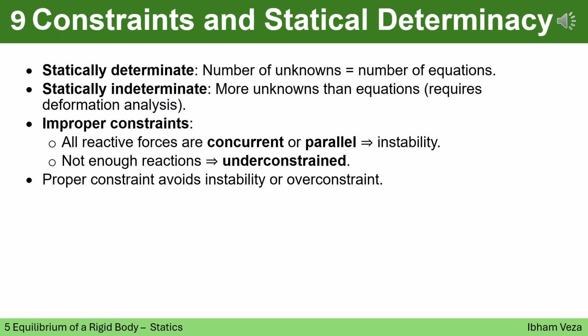Constraints and statical determinacy. An important concept in statics is determining whether a structure is statically determinate or indeterminate. A statically determinate structure has the same number of unknown reactions as available equilibrium equations. If there are more unknowns than equations, the structure becomes statically indeterminate and requires deformation analysis. Proper support arrangements are essential to ensure stability without introducing unnecessary constraints.